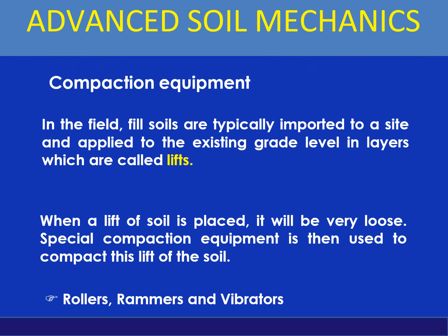Now we will talk about the compaction equipment. In the field, fill soils are typically imported to a site and applied to the existing grade level in layers which are called lifts. When a lift of soil is placed, it will be very loose. Special compaction equipment is then used to compact this lift of the soil. So rollers, rammers and vibrators can be used.